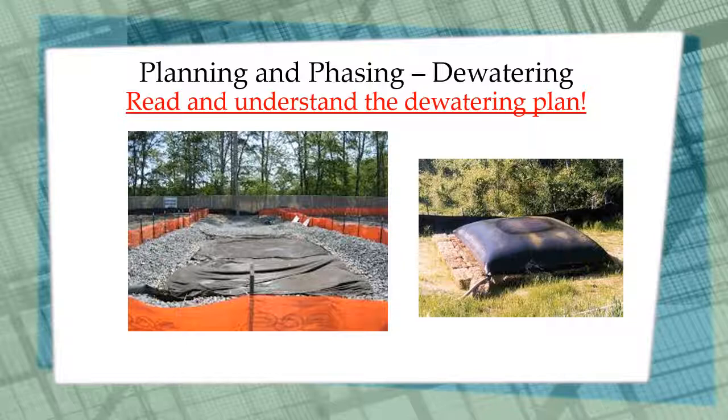When construction is getting ready to start on a project, talk with the contractor about how to phase the project to minimize exposed soils. Also, if there's going to be dewatering during the project, make sure that that dewatering plan is included with the erosion and sediment control documents approved by the city. If it was unknown at the time of the start of the project and it suddenly becomes an issue during construction, have the contractor stop and submit a dewatering plan for review and approval before they start work.